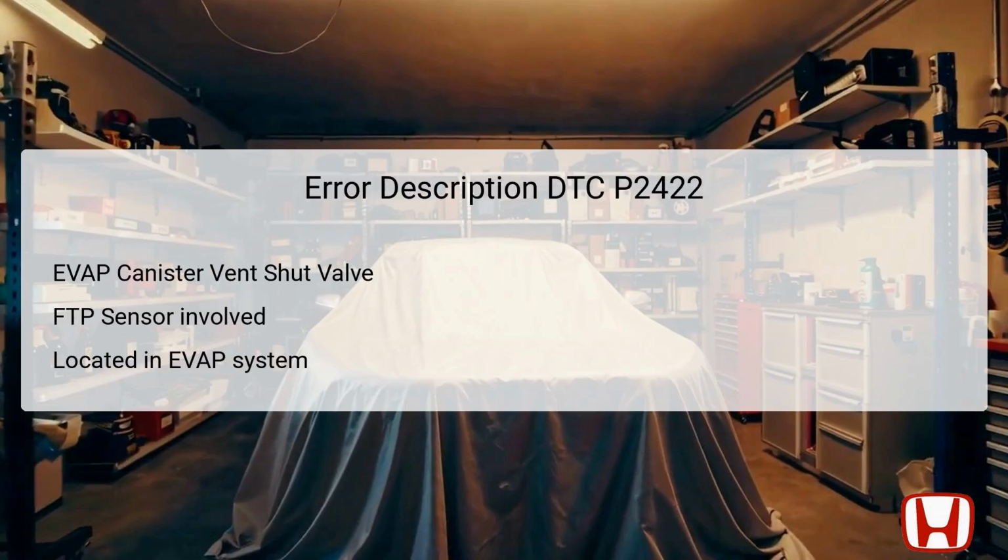The DTC P2422 indicates an issue specifically with the EVAP canister vent shut valve, which is a crucial component in the evaporative emission system of your Honda Civic. The EVAP system is designed to prevent fuel vapors from escaping into the atmosphere, thereby reducing pollution.